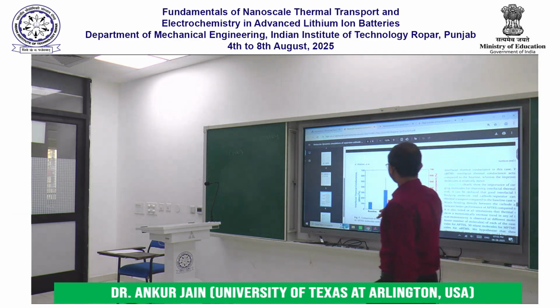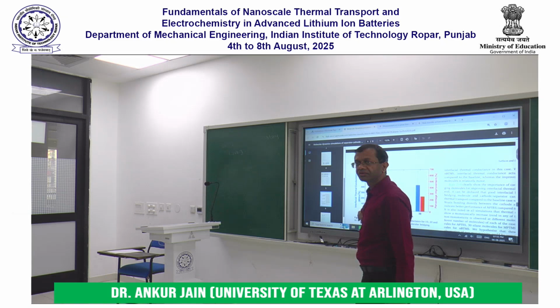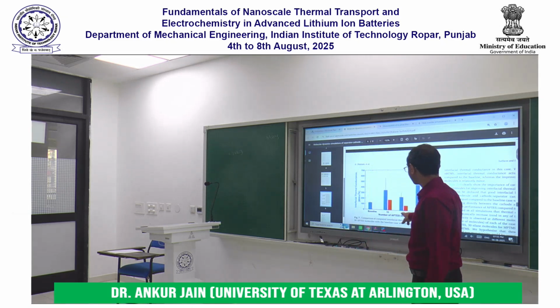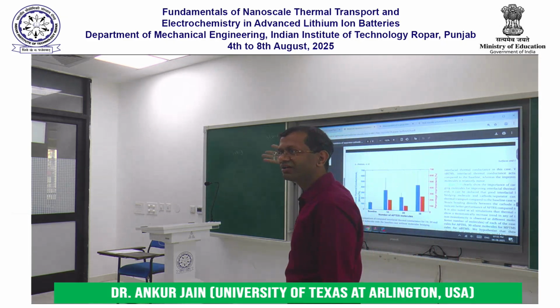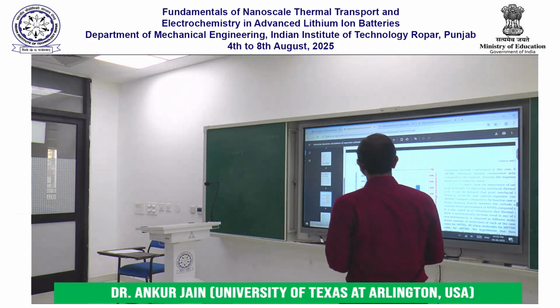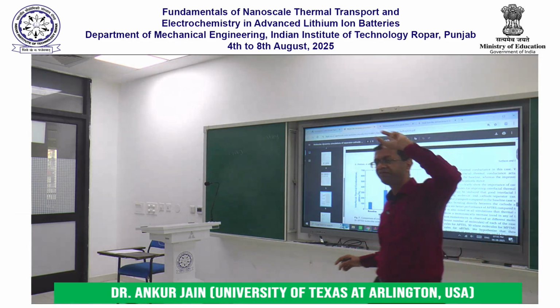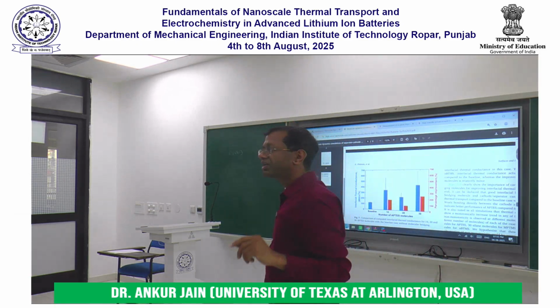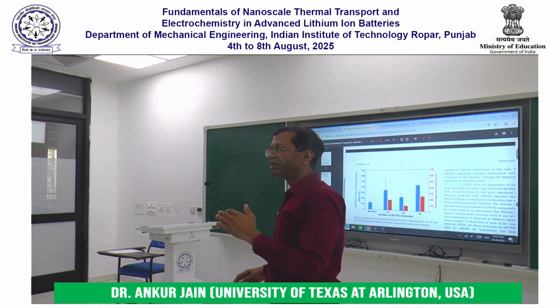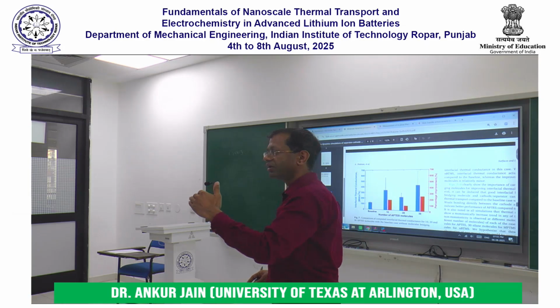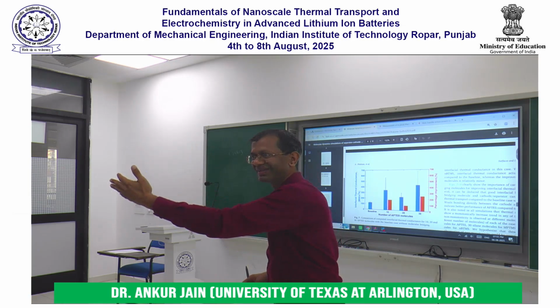He shows that compared to baseline, if you have 10 layers, 20 layers or 30 layers of APTES molecule, which is that aminosilane that I keep talking about, the thermal conductance, sorry, we need to flip our thinking. He's plotting conductance, not resistance. So do I want the conductance to go up or go down? I want it to go up, right?